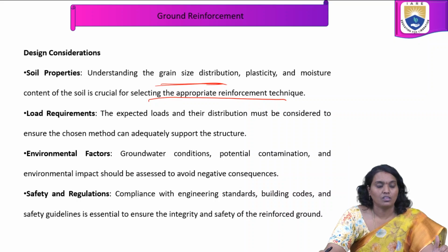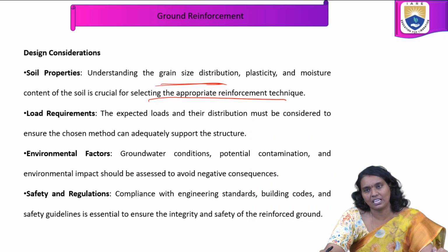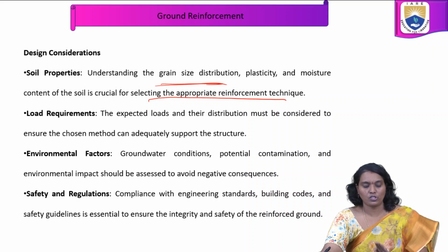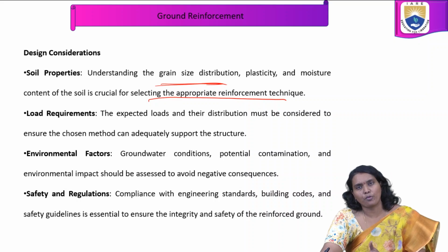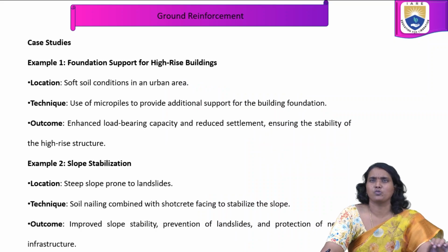Environmental factors: groundwater conditions, potential contamination and environmental impact should be assessed to avoid negative consequences. Safety and regulations: compliance with engineering standards, building codes and safety guidelines is essential to ensure the integrity and safety of the reinforced ground. Based on these regulations, load requirements and the soil properties, we are going to design the required ground reinforcement.